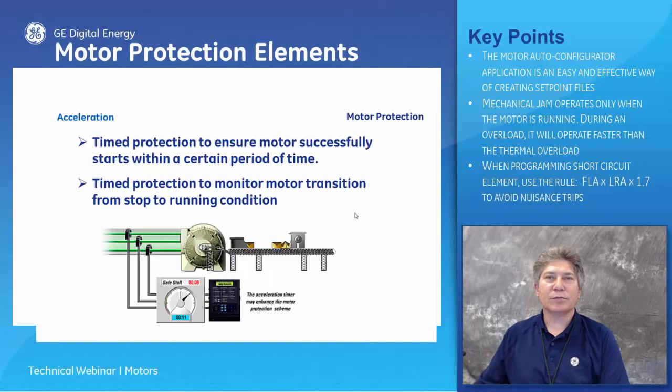Acceleration. This is time protection to ensure the motor successfully starts within a certain period of time. This is time protection to monitor the motor transition from a stop to a running condition.